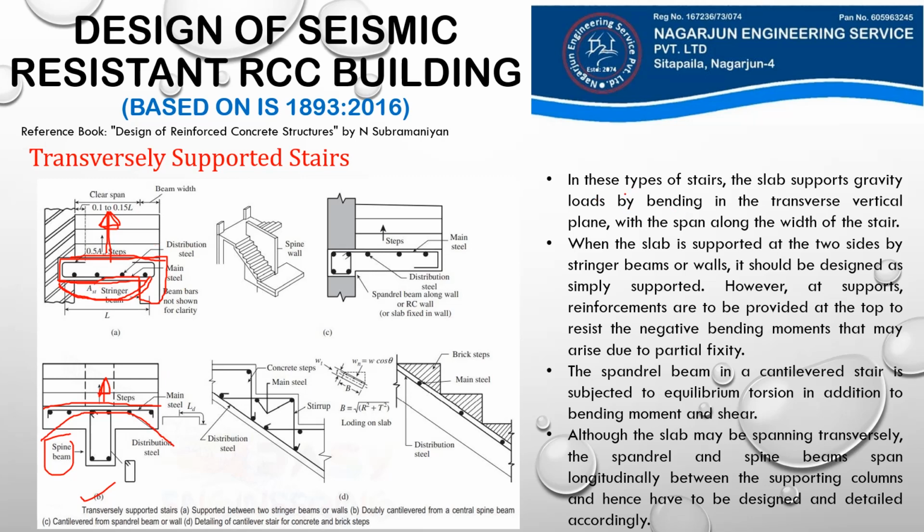So let's see here, in these type of stairs, the slab supports gravity loads by bending in the transverse vertical plane. This bending here, cantilever bending, this is also bending in the transverse vertical plane with a span along the width of the stair. I talked about it before. The width of our staircase acts as the span of our staircase.